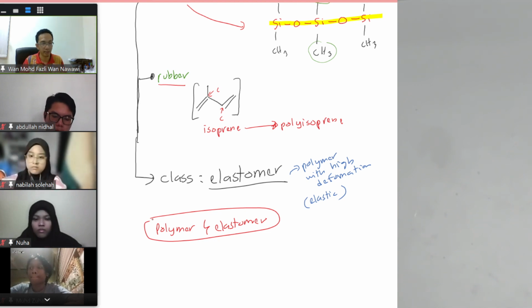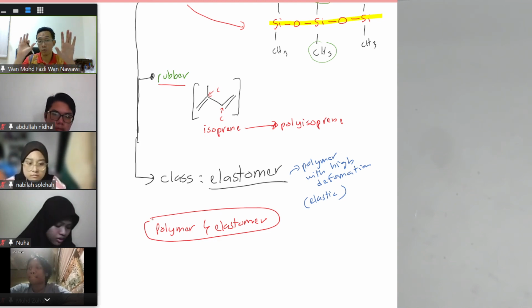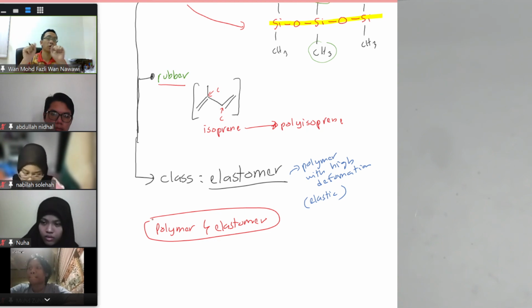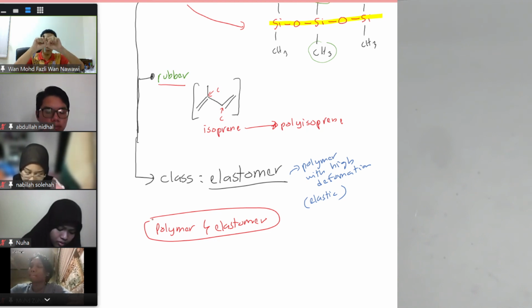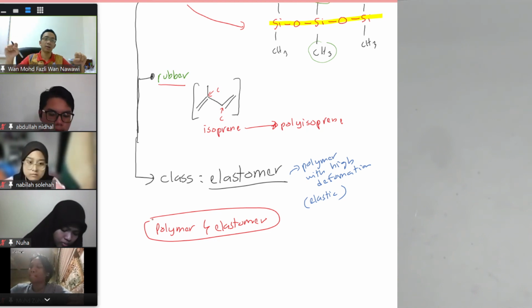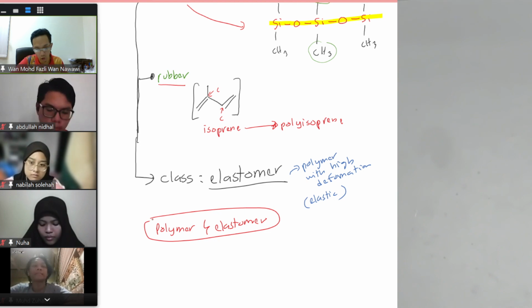You know that we have thermoset and thermoplastic, where you differentiate polymers based on temperature, but sometimes people also make a distinction in terms of whether it's elastic or not. You have normal polymer like plastic, and also elastomer. So elastomer is basically a special kind of polymer that has a high elastic region, like rubber and silicone.